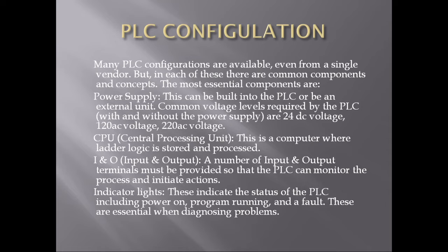CPU, Central Processing Unit. This is a computer where ladder logic is stored and processed. I/O, input and output. A number of input and output terminals must be provided so that the PLC can monitor the process and initiate actions. Indicator lights indicate the status of the PLC, including power on, program running, and a fault. These are essential when diagnosing problems.